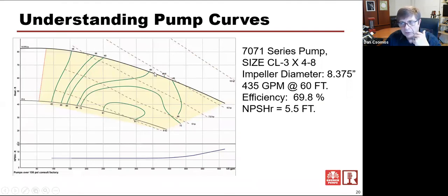If I did the math right there, I may have gone the other way, maybe 6 horsepower, but whatever that number ends up being, you would come back to the curve and say, okay, based on horsepower, I should be somewhere here. If you have any way of approximating or measuring flow rate, which is often difficult, you probably can't. Most systems you can't, but you generally have a pressure gauge.